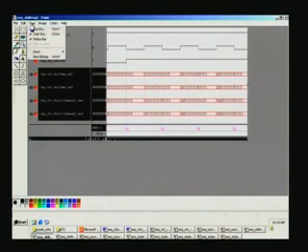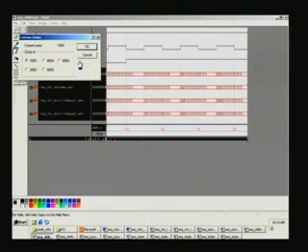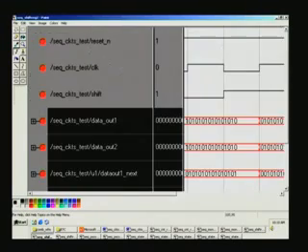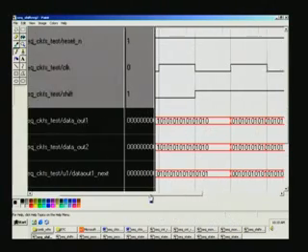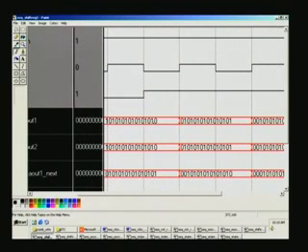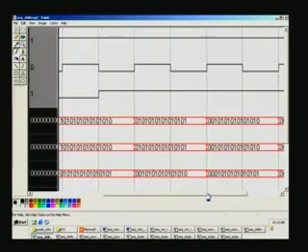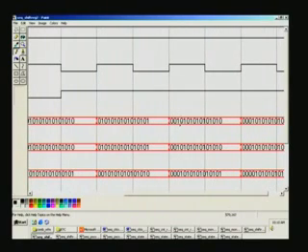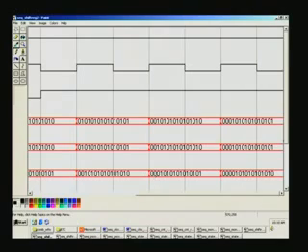So if I once again zoom in here. These are all the data out 1, data out 2. The first value was 1010. With the arrival of the next clock pulse, it has become 0101, and both are the same. You can just have a look all by yourselves. And then you keep on looking at it. See, two zeros, 1. So all the other bits are there. That means it's clearly right shifting here. And this is pre-shift. This will take effect only at the next stage, and so on it goes.